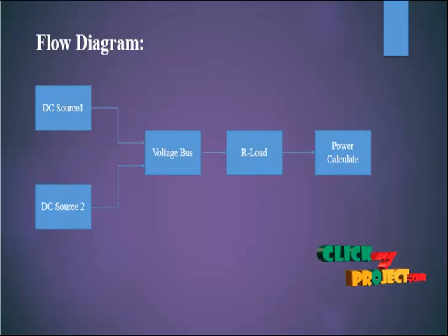The buck and boost converters are unidirectional, and the other line, a DC source, has a DC to DC buck and boost converting process that is bidirectional, from the voltage bus to the DC source, with both inputs 1 and 2 for power calculation. So this level is the main consideration for DC microgrid source analysis, optimization and the traditional droop condition of this process.